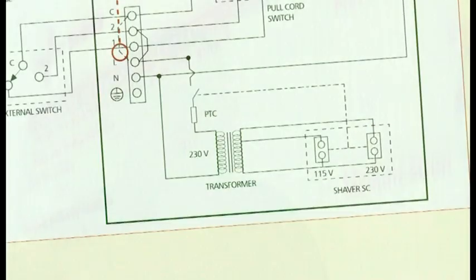Where electrical separation is used to supply an individual item of equipment, the inspector should verify that no exposed conductive parts of the separated circuit, such as any metal casing of an item of equipment fed by the circuit, is connected to the protective conductor or exposed conductive parts of another circuit or to earth.